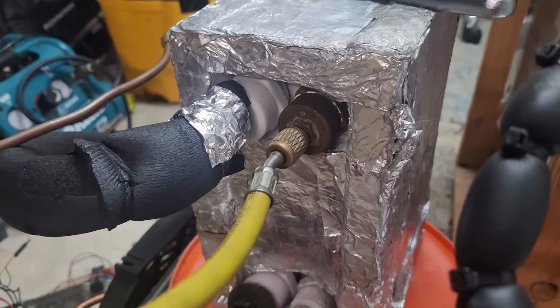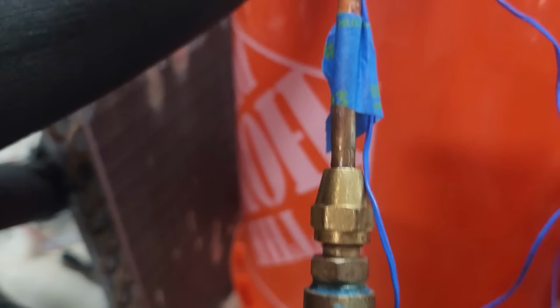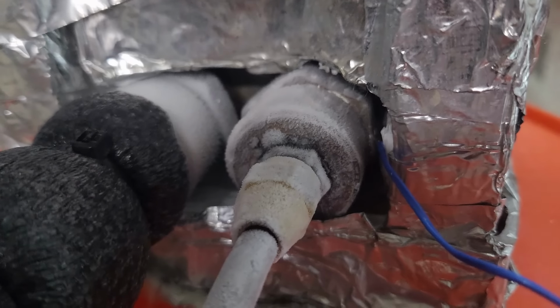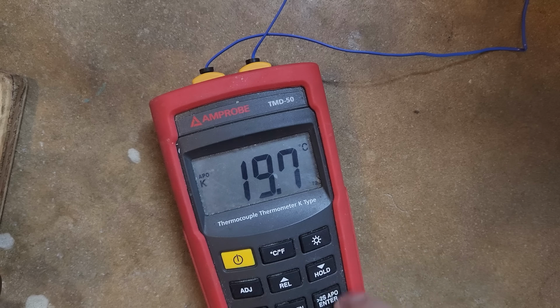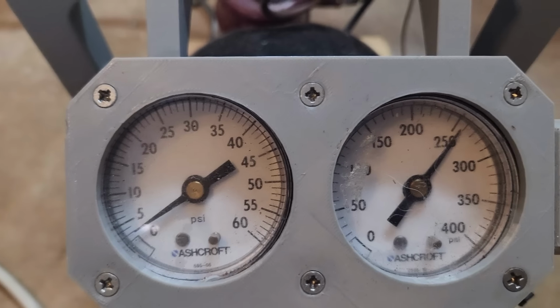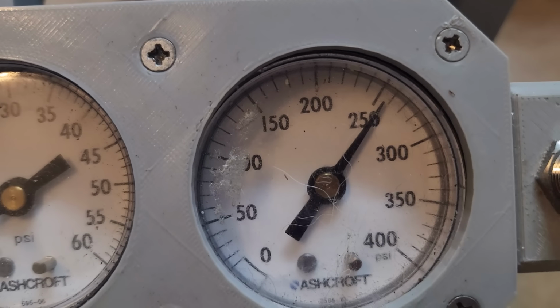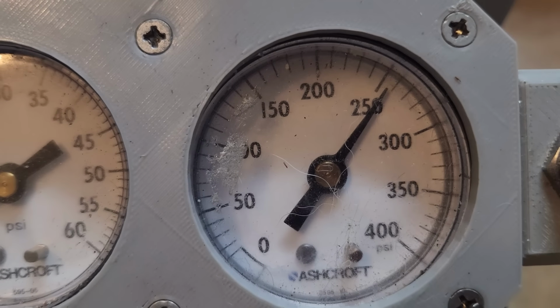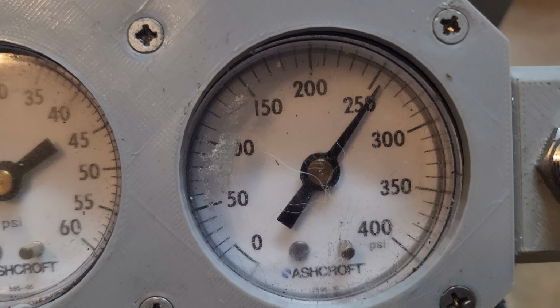At the top of the heat exchanger, I've got the output hose of the compressor, and on the bottom, I've got a copper tube attached to a valve with a naked thermocouple directly in the discharge path. Oh yeah, this thermocouple back on top measures the heat exchanger temperature. The current ambient temperature is about 20 C, and the heat exchanger is sitting at -12.6 C. After pumping the entire tank into the heat exchanger, pressure is about 255 psi or 18.6 bar, which corresponds to a boiling point of -10 C on the ethane, which seems more or less right. Considering that I've pumped about 100 liters into a space that's only around 300 milliliters, I'm pretty sure it's all liquefied now. Let's open the valve and let her rip.